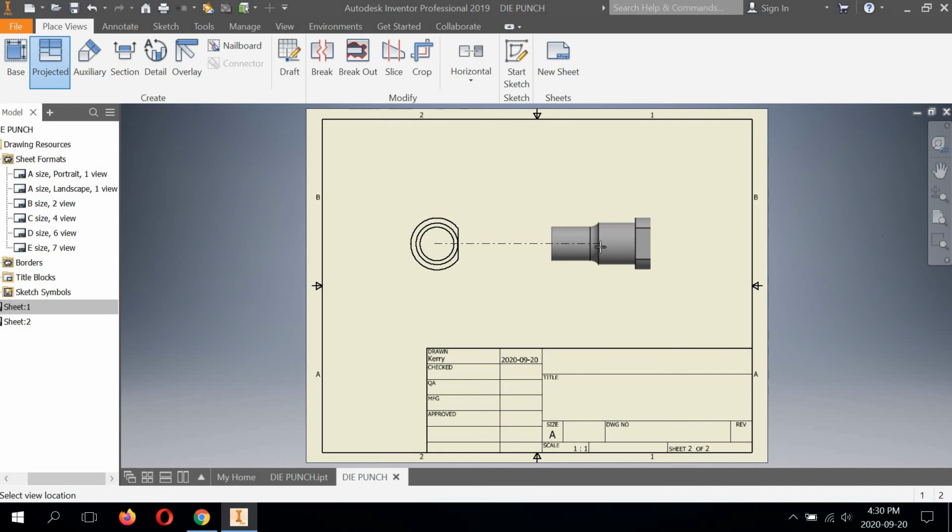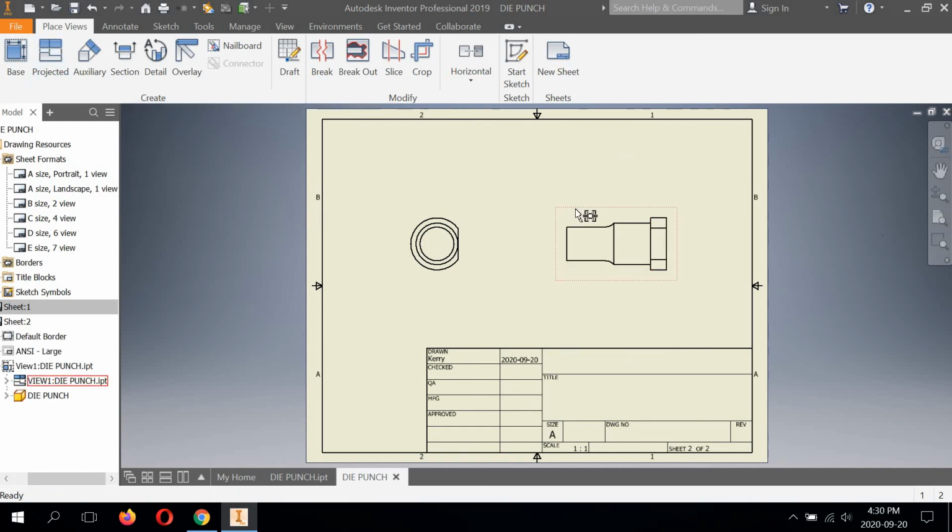And this view is also visible on your iPad in that die punch scan that I have up in the module. You can see both these views in line with one another. So I can left click and then right click and then left click create. And that's going to finalize that view.